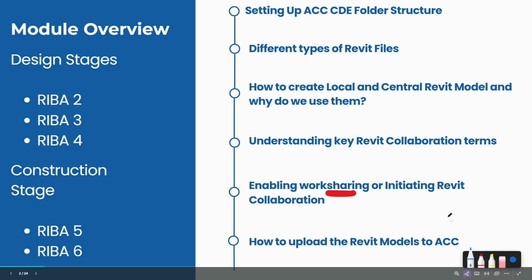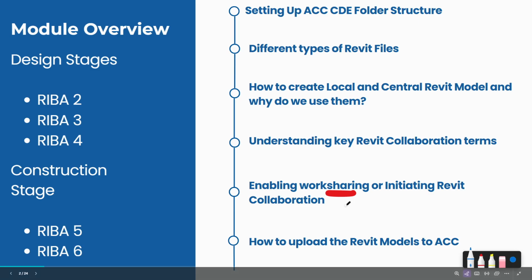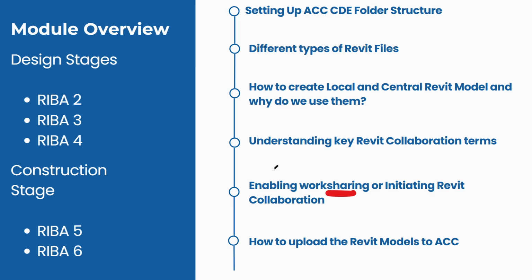Sunita, what were you saying? I mean, same thing, giving access and permission to share the documents. Yeah, that's correct. Only if one person is working on the Revit model, you don't have to enable work sharing. You can work on your own in your local server.